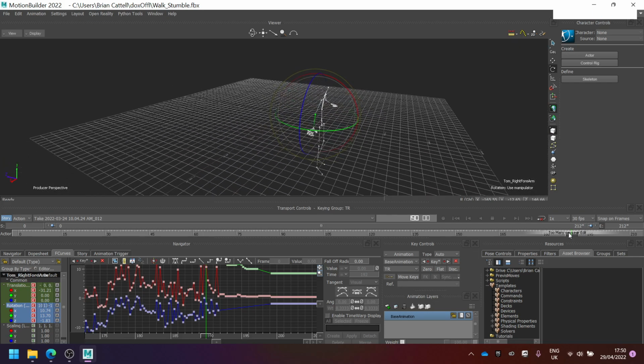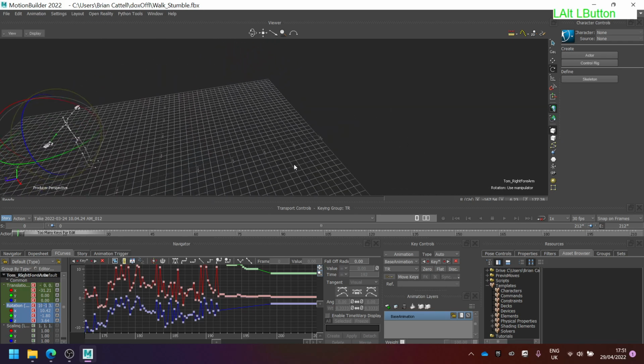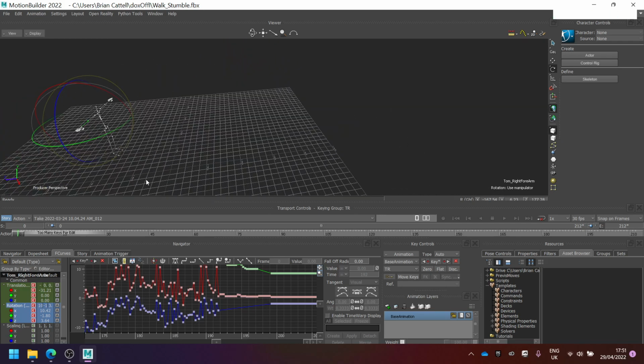Okay, so if I scrub this back, I'm going to need to do the rest of this from the frame 0 position. This is another thing: our mocap system, and certainly Motionbuilder, really likes T-posing. And if you've done an A pose for your character, you're going to have to correct that during this phase of operations. Okay, so I'm not going to characterize this yet. I'm going to bring in the other part of the equation, which is the character figure that we're going to map the motion onto.